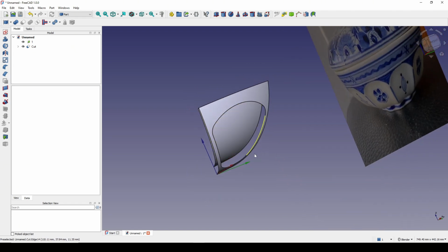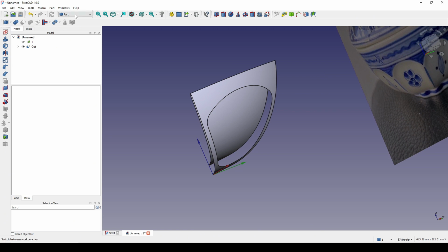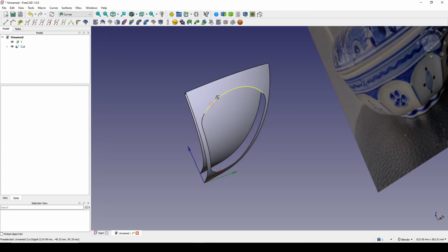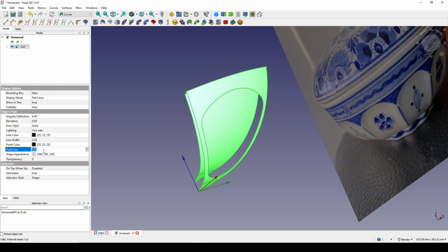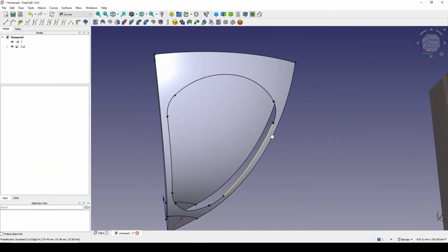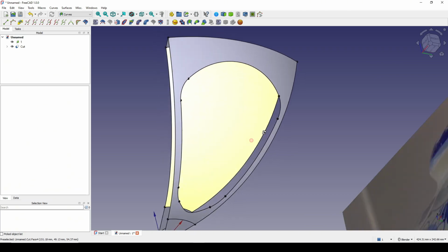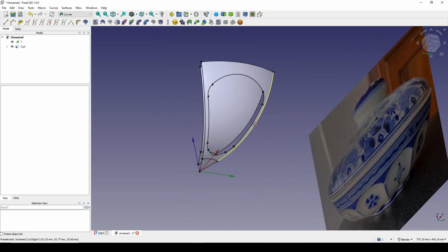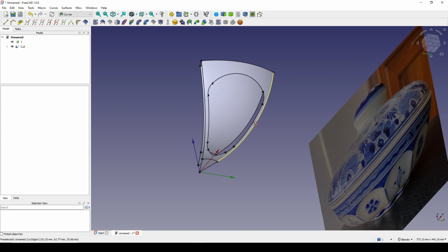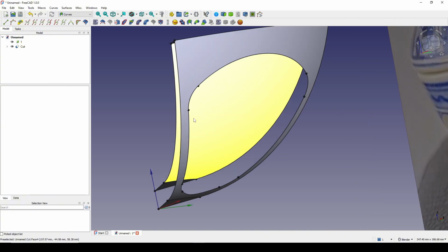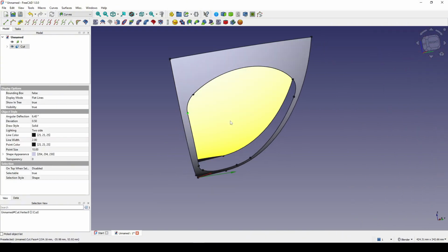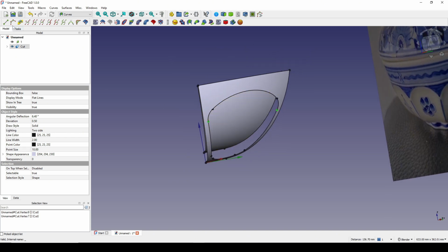So I just want one freehand B-spline on these 2 points above. So go to the curves workbench and click on the cut and go to the point size and set that to 10 to make the point size bigger to see what points I need to connect. So I will choose this point, control select this point and this point, and create a freehand B-spline.